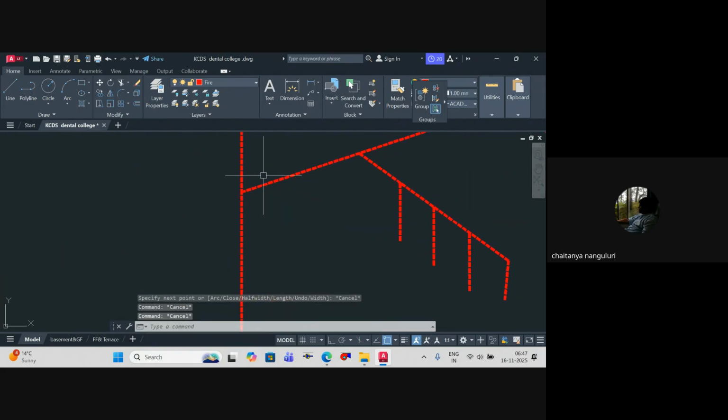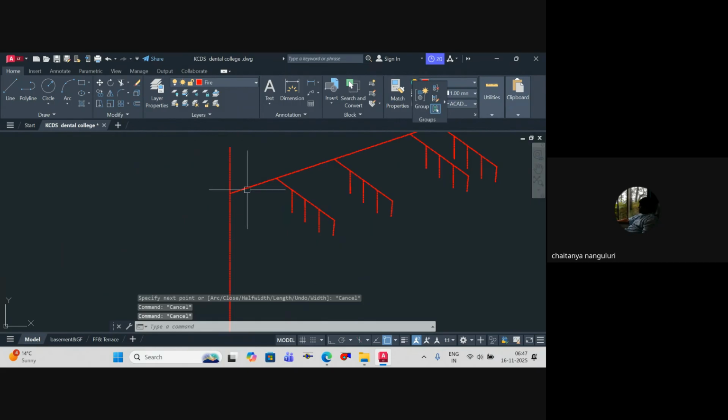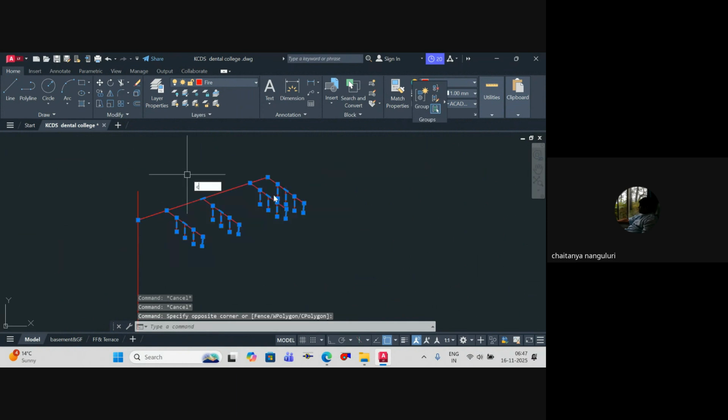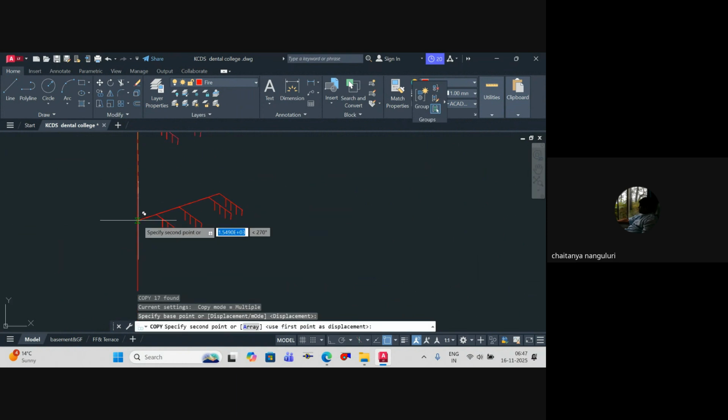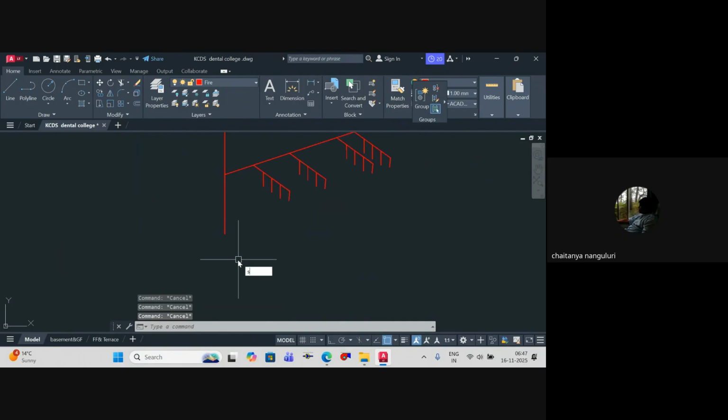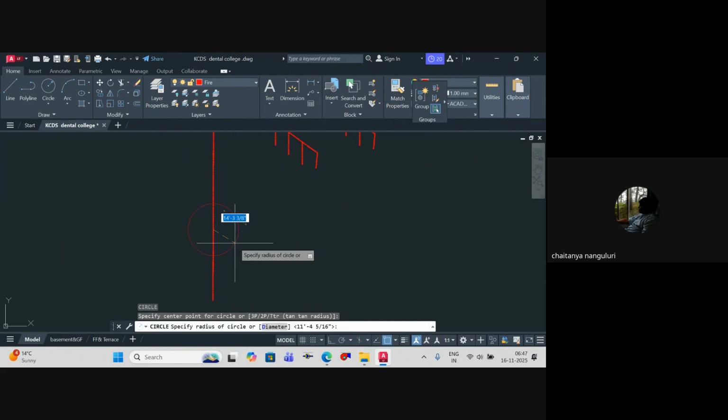One of the things that we do here is it's mandatory for us to install, in every zone, an alarm valve anyway. I'll just explain the schematic because every component I didn't show in the drawing, so I just wanted to show it. Let's take this as multiple floors we have. Whenever you are connected to the external hydrant or anything, here you will have an alarm valve.